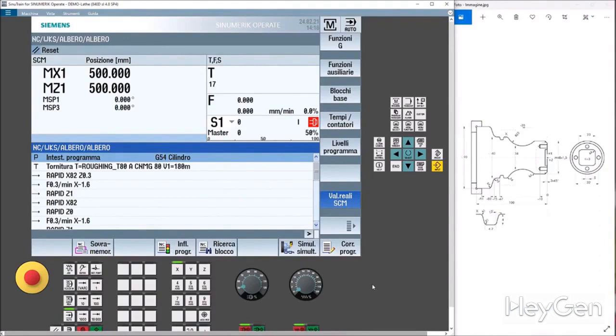With ShopTurn, we can define a casting, and that's really interesting. It really saves us so much time in programming, of course. When defining a casting, always stick to the maximum tolerance. Keep in mind that you will probably be clamping onto a raw piece, so the part might not be perfectly concentric.